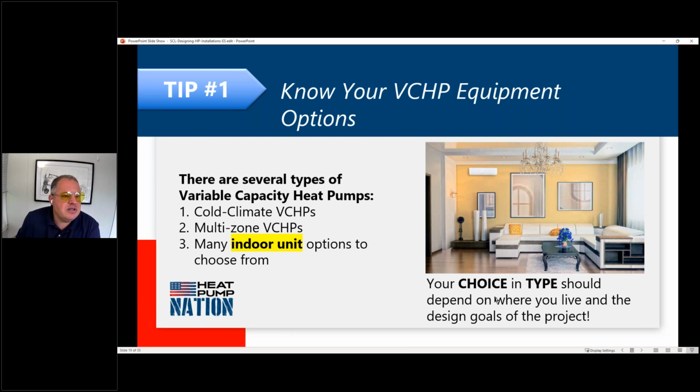So just to give you a hint on these indoor units, there are indoor units that can replace furnaces and connect to ductwork. There are units that can connect to ductwork, but you can install them in new areas, like in a small part of the home, in an attic or in a closet, and just serve a couple of rooms. There's ductless style indoor units that go high on the wall. There's ductless style units that go low on the wall. There are ductless style units that can be hidden in a closet and serve just that one room.